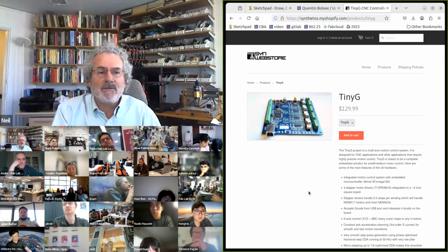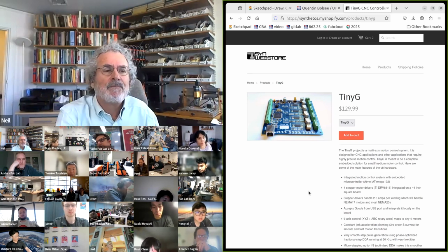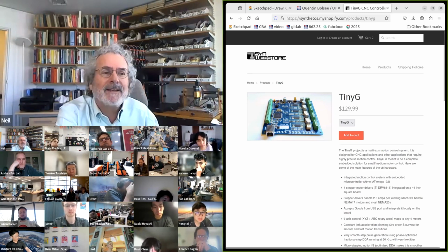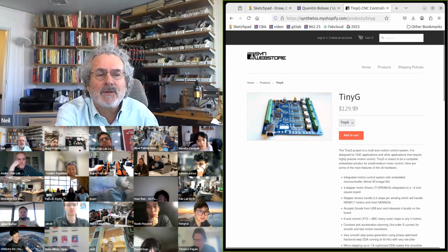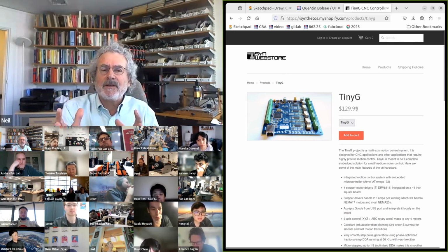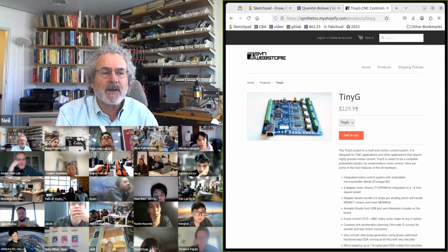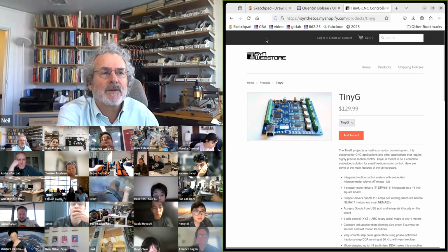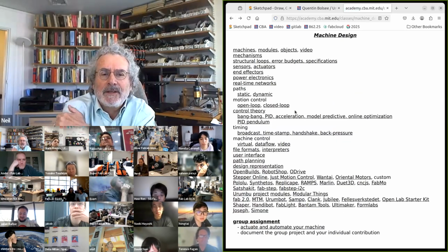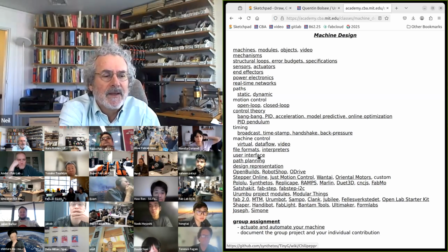It's handy, it's convenient. This one board, you connect your motors and send your G code. On the other hand, you have to map the G code commands into what your machine does. And it looks very different if you have a Delta bot or a Core XY. And then there's no scalability. If you need one more motor, you're out of luck. That's what the board can do. So they're commonly used for standard solutions, but they're not flexible.